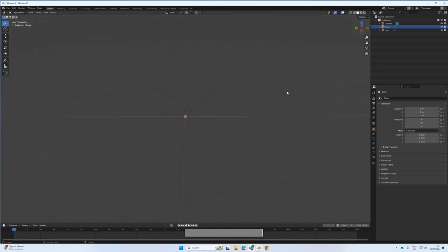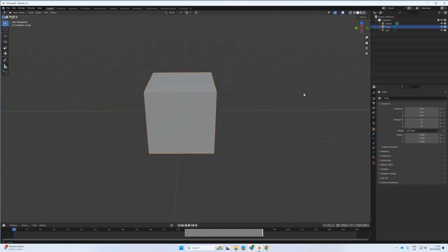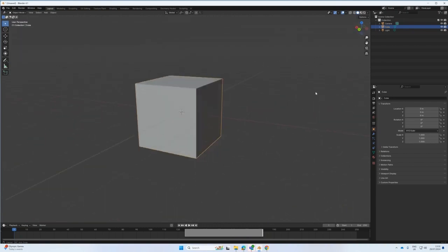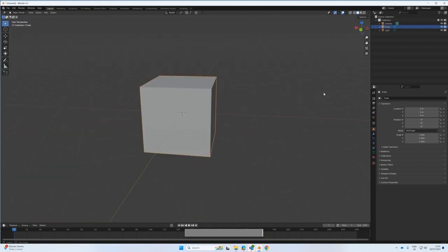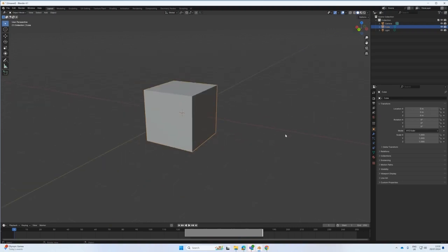So scroll out, you zoom out, scroll in. Yeah, so it's the same as the Control, but then you can do it by scrolling as well. Okay, so now I am just pressing my mid mouse button and rotate. Okay, so have a go at this a little bit, practice a little bit. Okay, and then we're gonna start.